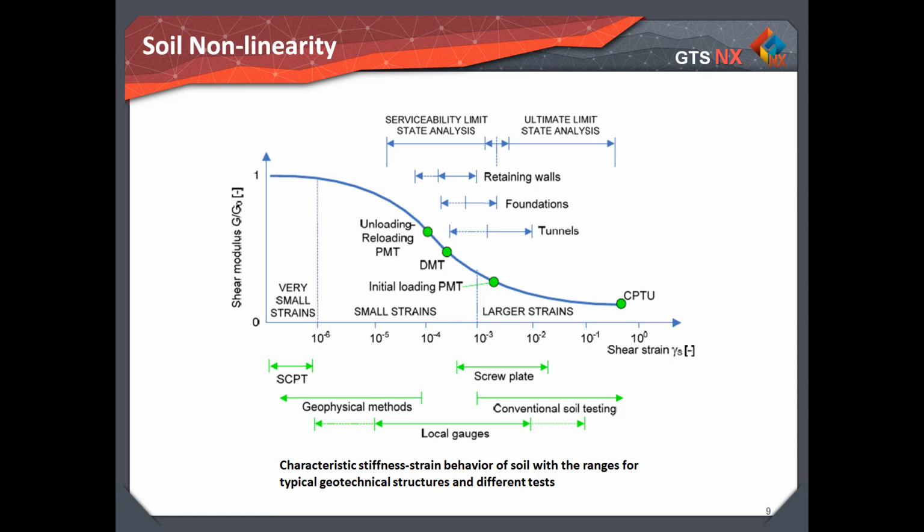Relevance of small strain stiffness: very stiff behavior at very small strains, vibrations, reduction of stiffness with increasing strain, restart after load reversal, hysteresis in cyclic loading, energy dissipation or damping. Also relevant for applications like excavations, settlement behind the retaining wall, or tunnels, settlement above the tunnel.